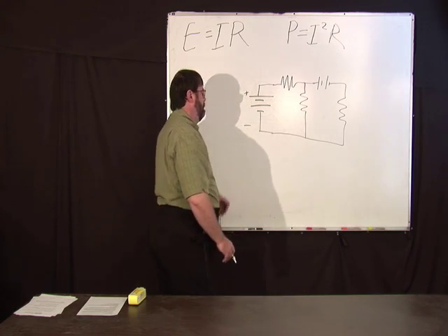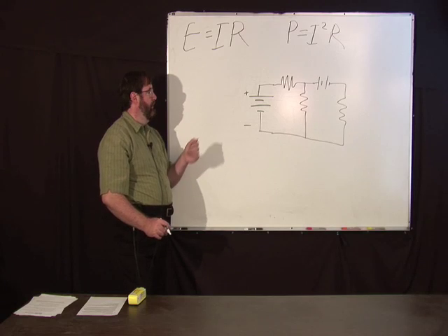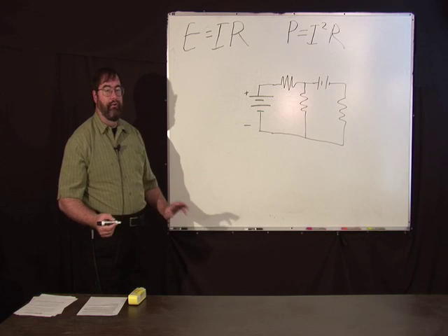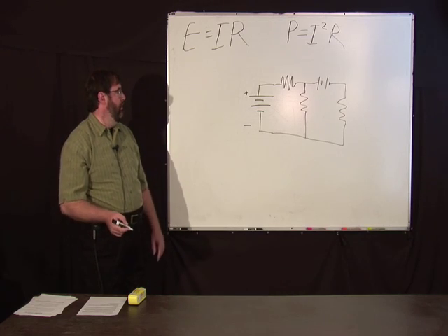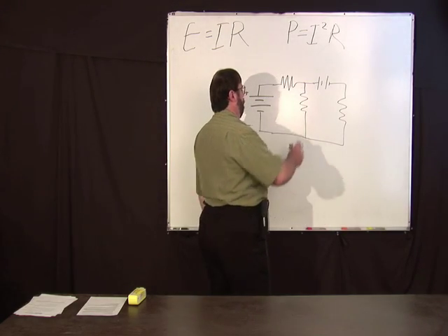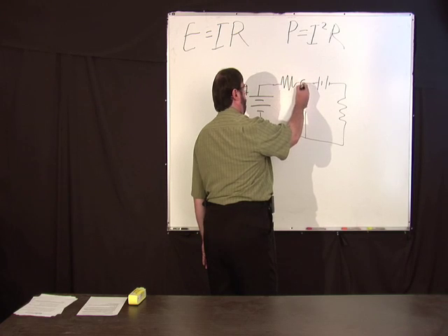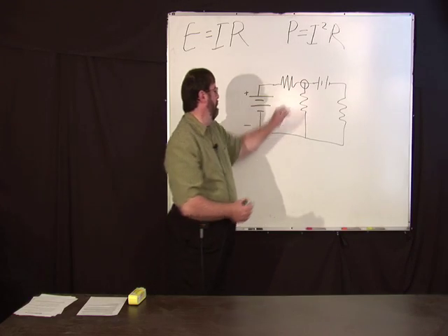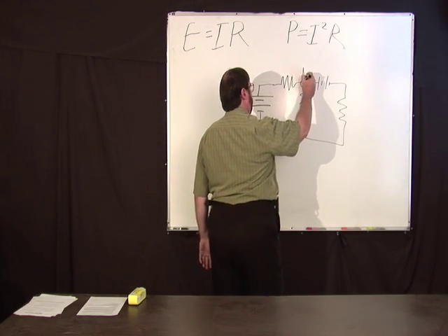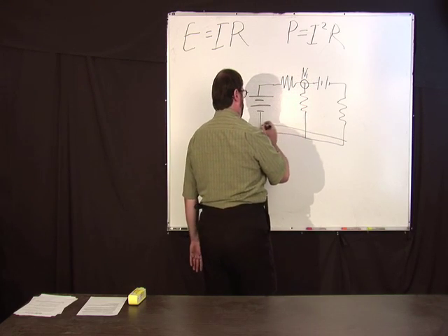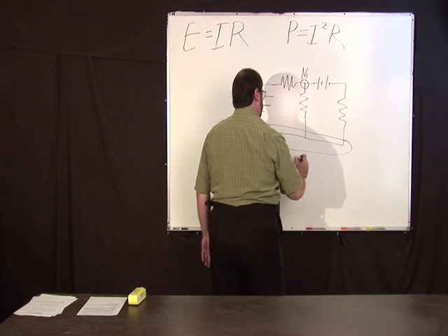And what you do is you start out with a circuit. First thing you want to do is identify the principal nodes of a circuit. Principal nodes of a circuit are places where more than one wire is connected. Now, here's one. We'll label this node 1. And this here, since it's all connected by wires, is really just one big node. We'll call it N2.